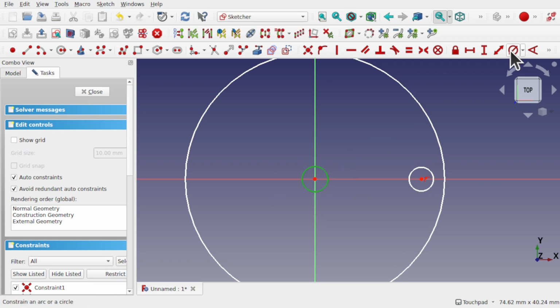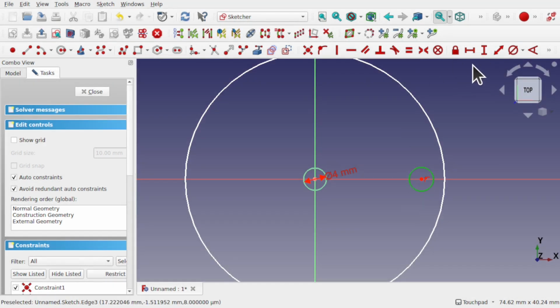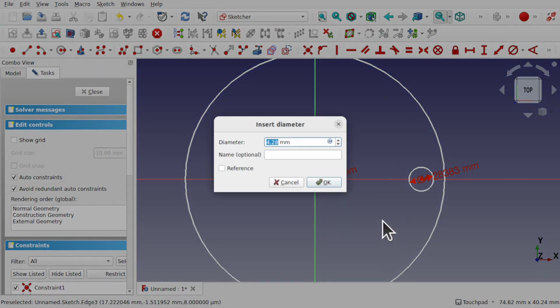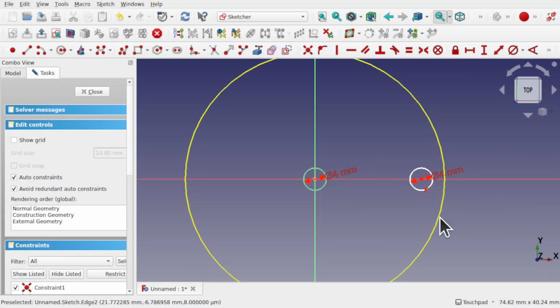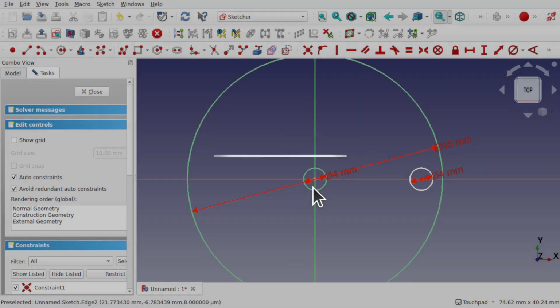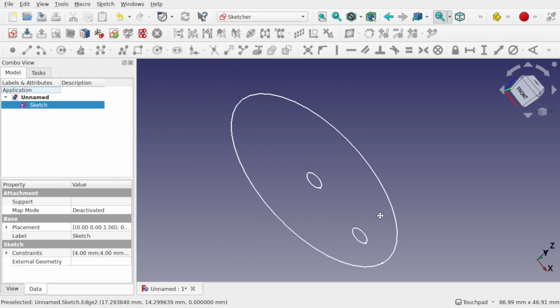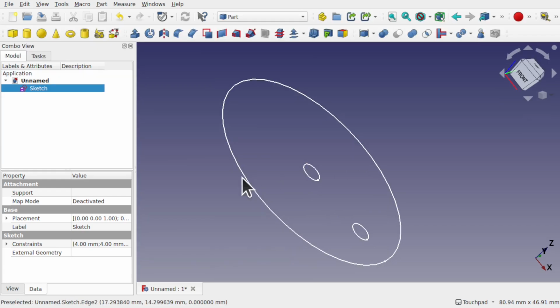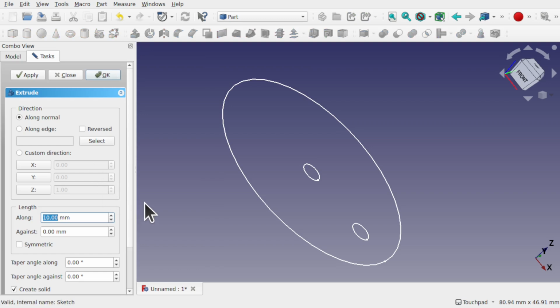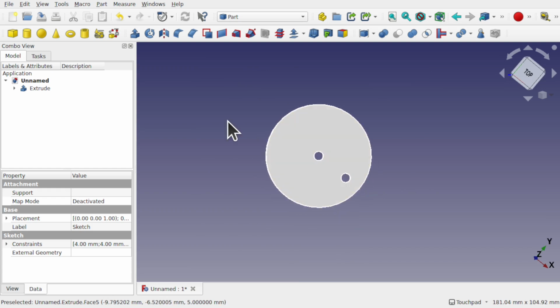So we'll rotate around this circle here, which we're going to set to 4 millimeters, and also something's going to be attached to here, so it can drive something else. And we'll set the outer circle as well. Set that to 45, and we'll set this some distance away from here to here, and 15. So we've got that. Let's come over to the part, and we'll just extrude that by 5 millimeters. So we've got our first part, which is the extrude.